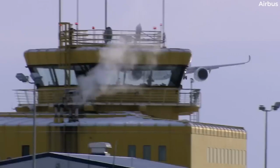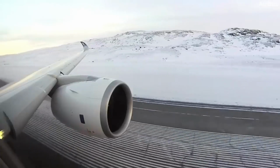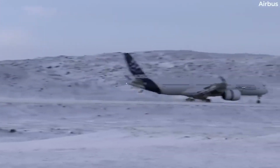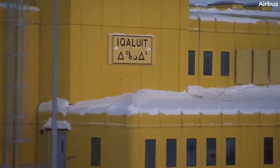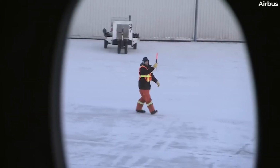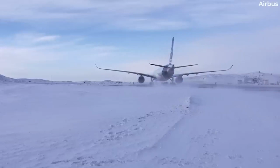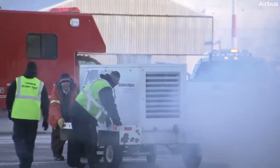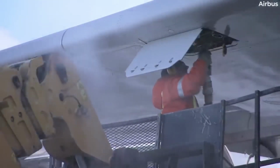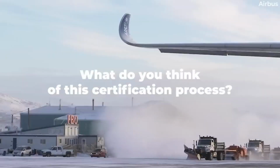14 CFR Part 135 Operating Requirements: Commuter and On-Demand Operations and rules governing persons on board such aircraft. As the title of this section states, this regulation is applicable to short-distance commercial aircraft operations or commuters and non-scheduled carriers that operate on demand. These aircraft are frequently referred to as air taxi or air charter aircraft. Aircraft operated under 14 CFR Part 135 must be operated and maintained in accordance with the certificate holder's operations manual. This manual, when accepted by the FAA, specifies how the flight crew, ground personnel, and maintenance technicians conduct their operations.